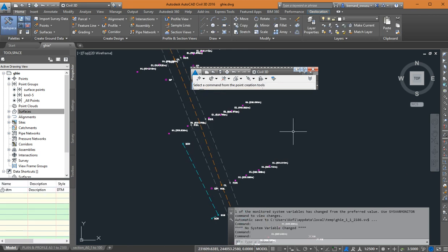What happens when you click on OK? Nothing happens. Okay, and in the surfaces, you see that there's a plus attached to surface, which means that you have some things under it. So click on the plus and you should have the surface that you created, DTM. Please, do you have it there? Yes, but it's empty. You've created the name alright, but we are here to add data to it. So we are now going to add data to it. Please, are we okay?